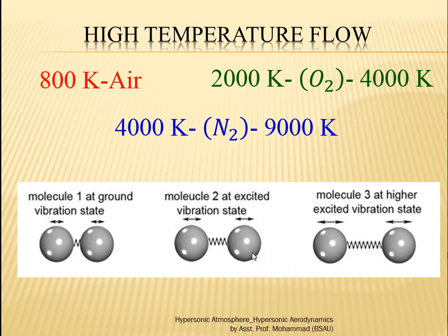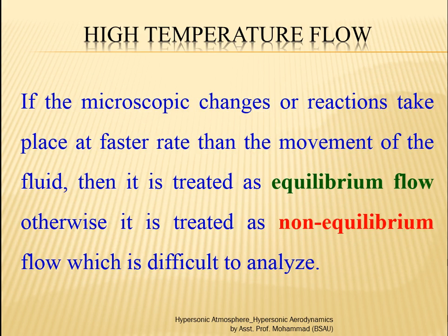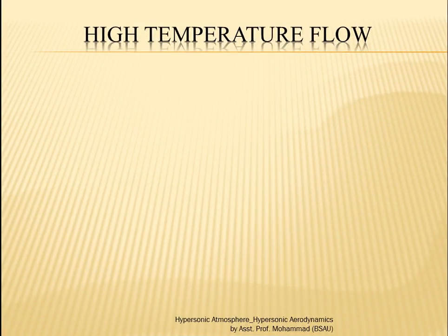All these difficulties are collectively termed as high temperature effect, and also frequently referred to as real gas effect. Although for some technical reason we don't like to call it real gas effect, because everything is real, it's the high temperature which is causing all these things to happen. If the microscopic changes or reactions take place at a faster rate than the movement of the fluid, then it is called equilibrium flow. Otherwise, it is treated as non-equilibrium flow, because these two movements are comparable to each other, so they both start affecting. So they are not in equilibrium, and that is difficult to analyze. We have seen this already.